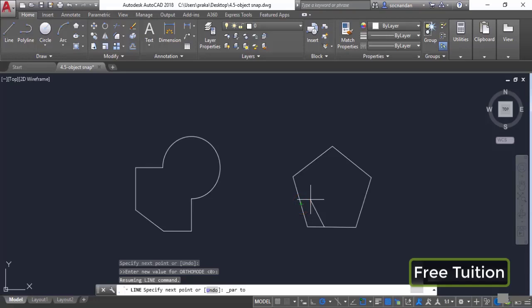Now move your cursor, and when the line becomes parallel, this green tracking vector will appear. Now you can click anywhere to make this parallel line, or you can also enter the distance. So let's say that we want to make it of length 50 units. I'll type 50, press Enter, and Enter again. And we have this line exactly parallel to this one.